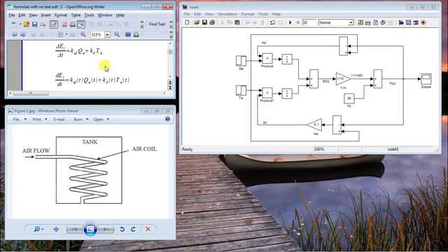This is easy. The closer the liquid temperature gets to the air temperature, the less influence the air temperature has over the liquid temperature, which means that KTL approaches zero. Even more, if these are equal, there is no more energy transfer, which means that KTL is exactly zero. And even more, if the liquid temperature somehow gets higher than the air temperature, then the air will cool down the liquid temperature, which means that KTL will become negative.